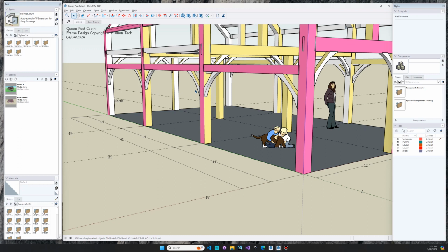And then there's two features to speed up your workflow. They are to create all the shop drawings in one go. So this is big: make shop drawings in batch mode. And then instead of sending the shops to layout one at a time, you can also do all of them at once using batch mode. It'll just find all of them in the current folder and send them all to layout all at once.